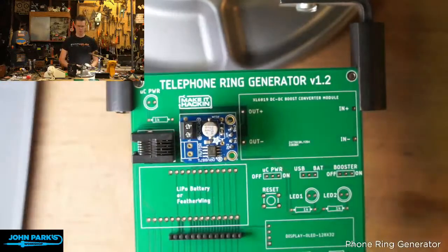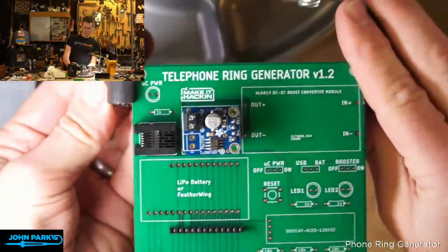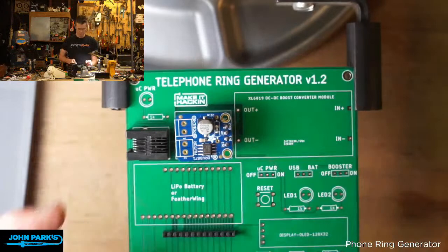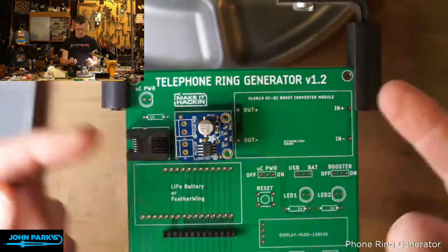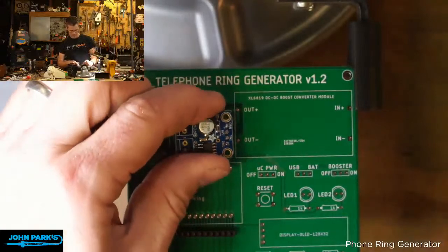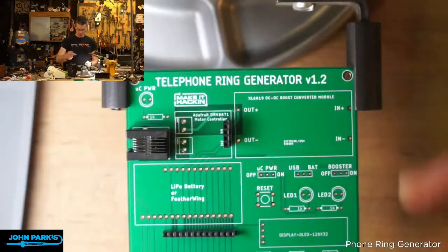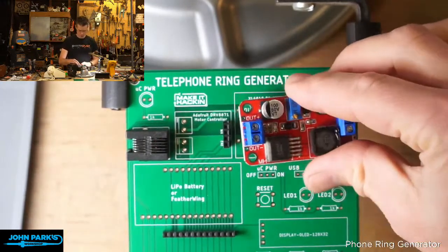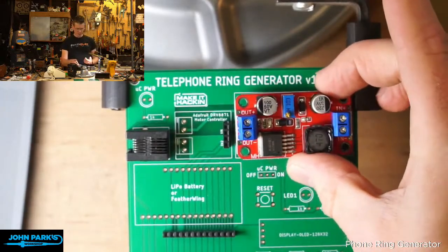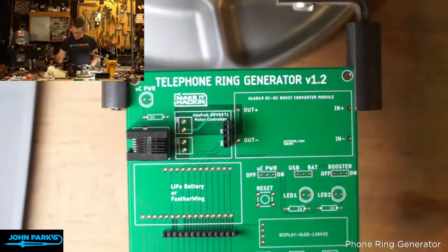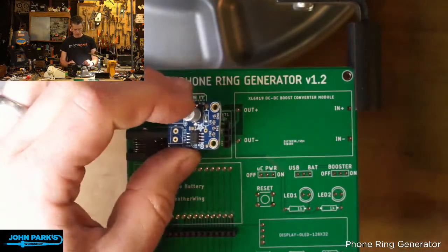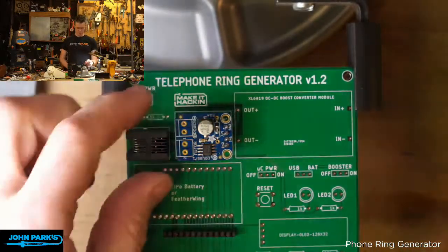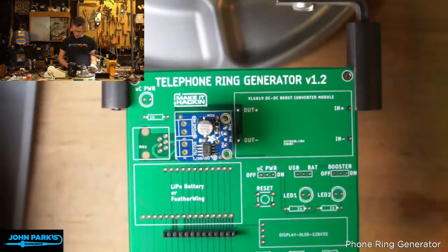And so I just kind of want to make sure that one of those things isn't in the way of another, but since this is on a removable header, it's going to be pretty straightforward to do it in any order. But here's the case, this header here, is there anything there that needed to be soldered that's tricky? That's going to be the boost converter, which is going to go there, and that's just on 4 header pins. We could again do some removable stuff. I might do that. It's not as secure. It's more secure to just solder things straight to the board. So it's up to you if you want to use sockets for everything. Okay, so that should work out fine there.